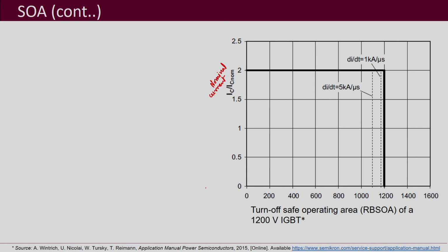Now usually what happens is that in IGBTs or all these power semiconductor devices, there is not just one chip inside the IGBT. There may be several small chips connected in parallel, and that forms one device, which is what you obtain from the outside as the case, and the ratings correspond to that one device, where actually you may have several small chips connected in parallel.